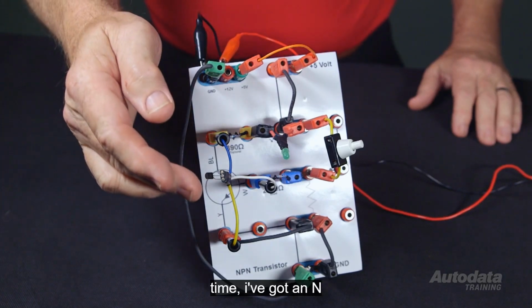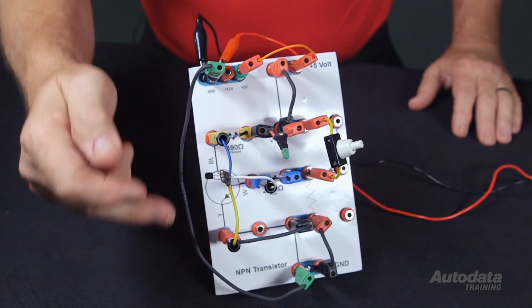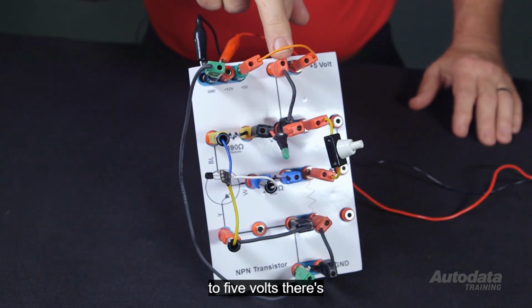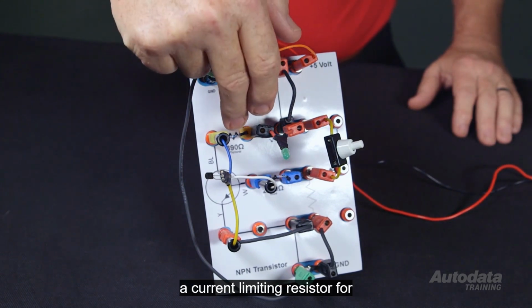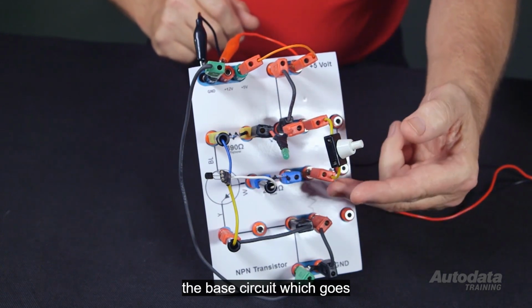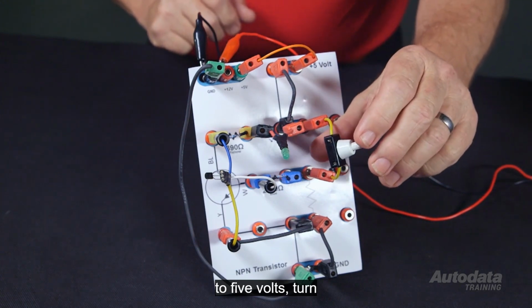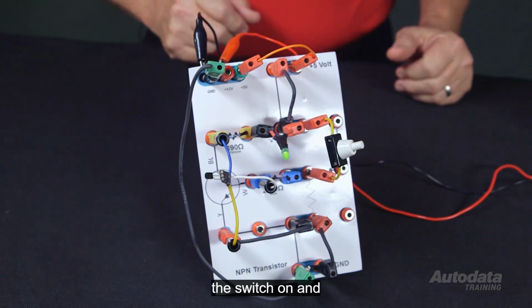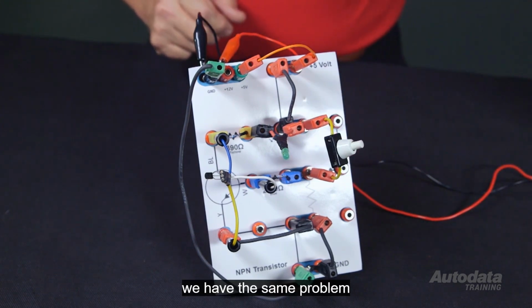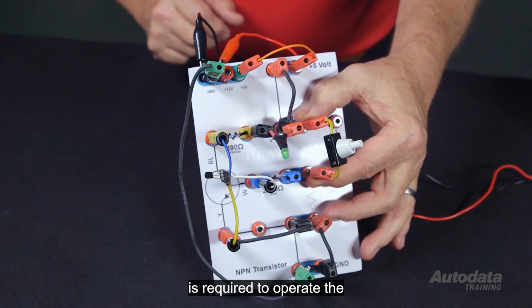This time I've got an NPN transistor. The emitter is connected to ground, and the collector is connected to our load, which goes to 5 volts. There's a current limiting resistor for the LED, and a current limiting resistor for the base circuit, which goes to our switch, which goes to 5 volts. Turn the switch on, and the LED comes on. We have the same problem. Very little current is required to operate the circuit.